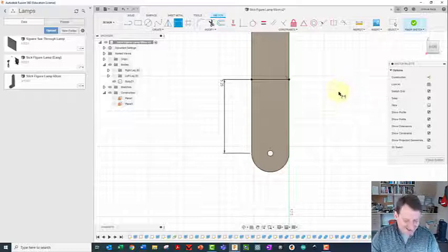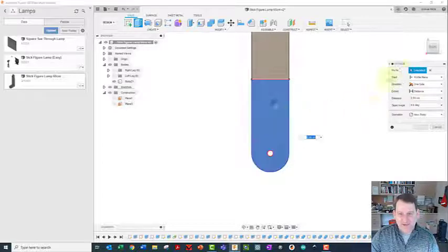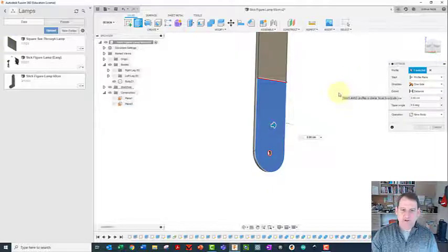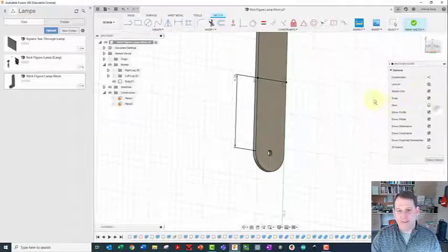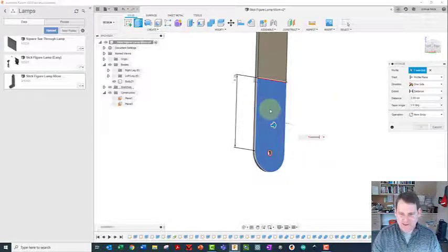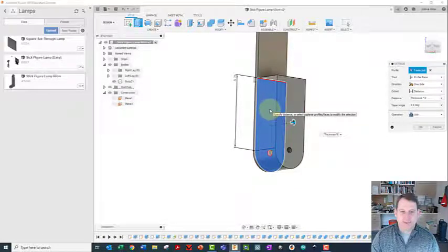Now I'm ready to extrude this already, actually. So I'm going to click here. I'm going to say extrude. And notice the hole is there already, which is kind of cool. And I'm going to extrude this towards me. And I want to do 8 layers towards me. So I'm going to do this as thickness. Whoa, what just happened? I don't know what just happened. So I'm going to extrude again. And I'm going to go thickness times 8. Times 8. And enter.